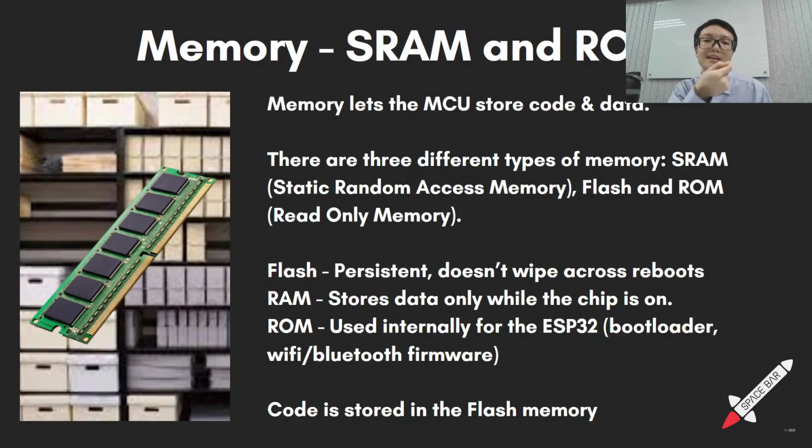Okay, so memory is in the microcontroller. As a programmer, you will deal with 3 types of memory, which is mainly the stack, the heap, and static data. Static data is your global variables, and stack variables are essentially the variables you declare in functions. And the heap is managed by the programmer using a special function called malloc.